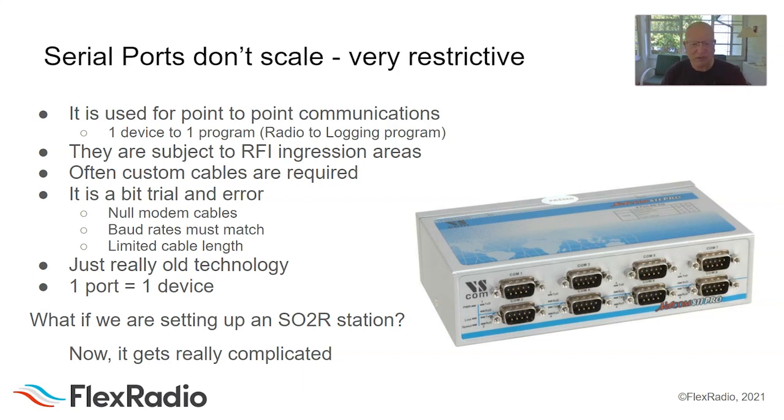And as I mentioned, sometimes you need null modem adapters because it takes a minimum, generally, of 3 wires to communicate with a piece of remote hardware. Or by remote, I mean hardware that's not part of your computer. And it's just really old technology. And if you're setting up a station like an SO2R station, that's a single operator 2 radio station where you've got 2 radios going at the same time and 2 amplifiers and stuff, it's a lot of work, and it starts to really get complicated.